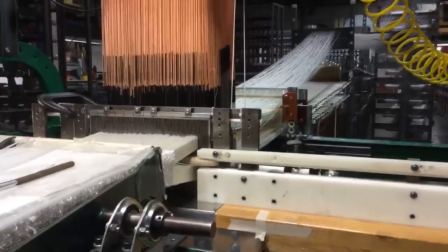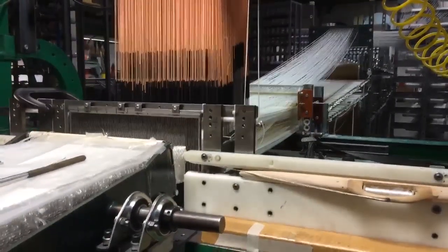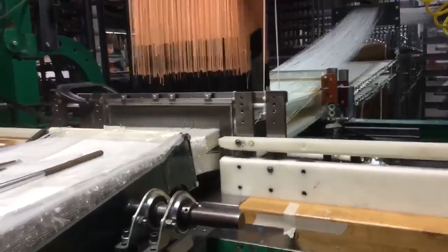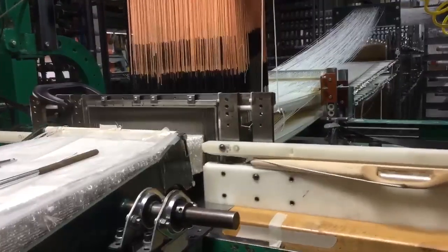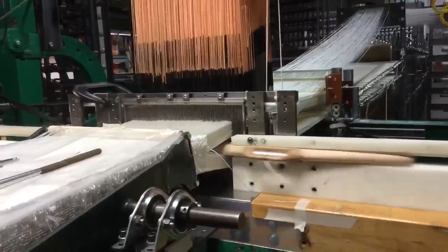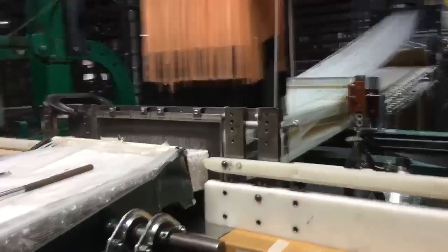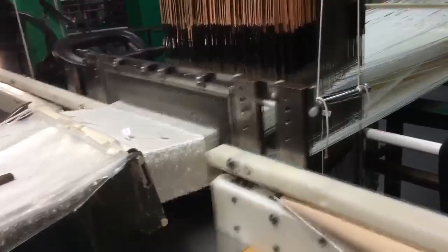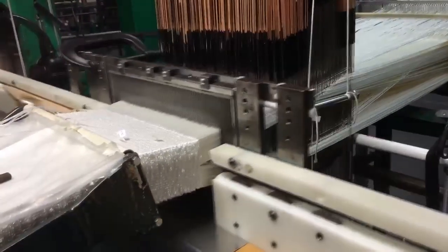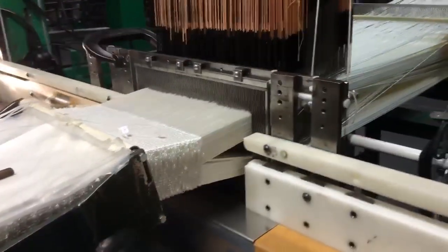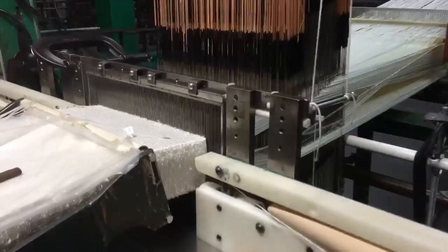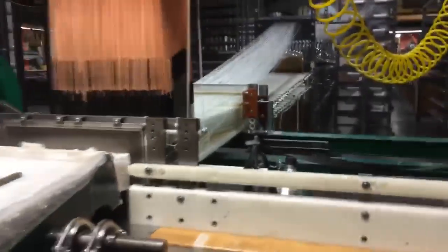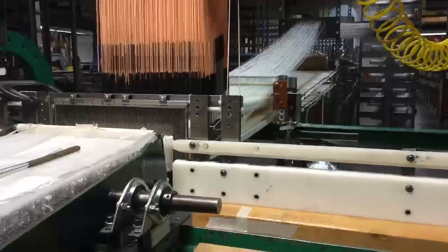Okay, here we go. So this is the loom in action. I mentioned you see the shuttle going back and forth here that contains the fill yarn. It has to go back and forth for each one of the layers in this material in the Z direction. It's built up about 50 layers in the Z direction. It has to go through each one of those 50 layers before the loom can advance one step in the X or warp direction. So it's a very slow process to weave this. A 13-inch long part takes on the order of a day of continuous weaving.